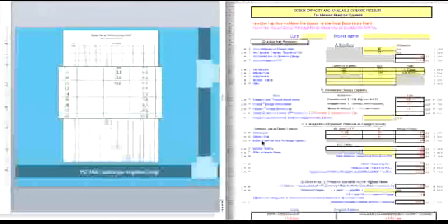So there's also some pressure loss from the water meter at the given design capacity, and the worksheet has already entered that as 1.84. And that kind of brings me over here to this slide. I wanted to show you that there is a pressure loss chart for water meters in your textbook, and the basic pressure losses for the water meter were pulled from here for this portion of the worksheet.